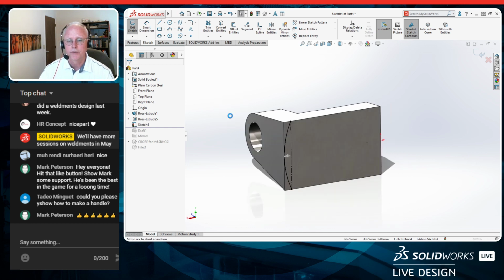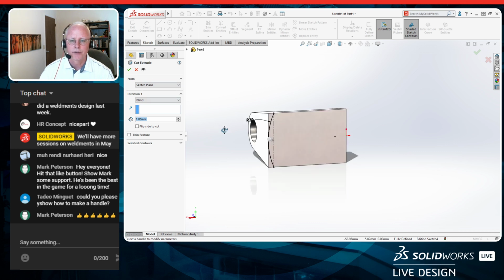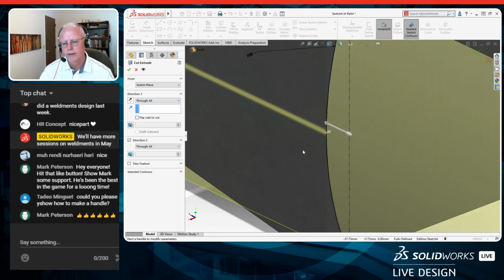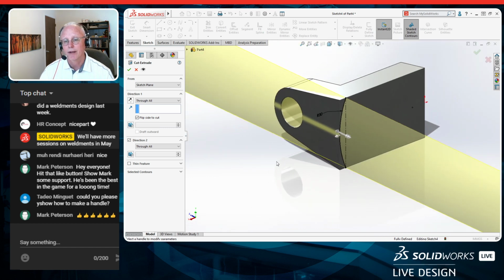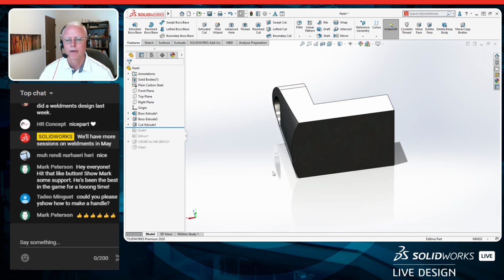So what we're going to do is just use the shortcut bar, bring up my cut extrude tool, and a couple things to notice here. So I want to cut this through all, of course, but see this extra little arrow in here? That's the flip side to cut. So it tells me which side I want to cut. I can choose it on screen, or I can choose it over here. Doesn't matter. But what I want to do is cut the material away to the outside. Makes sense, right? So we'll go ahead and cut that material away. That worked out good. We have that 30 millimeter arc on there.